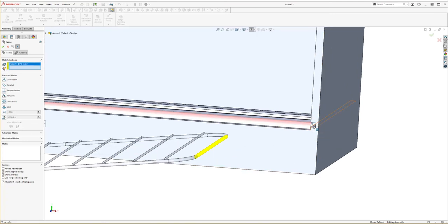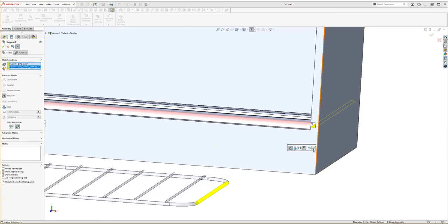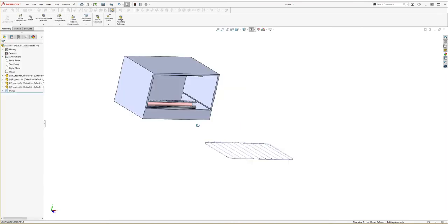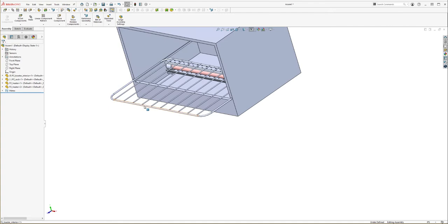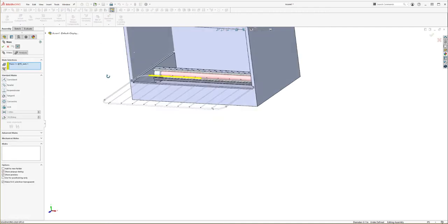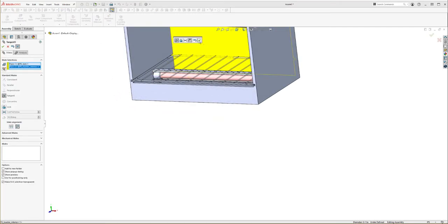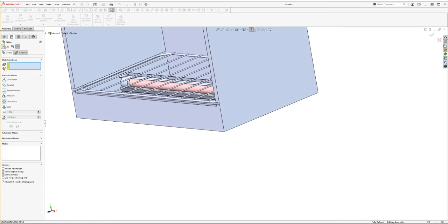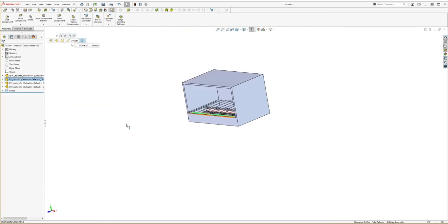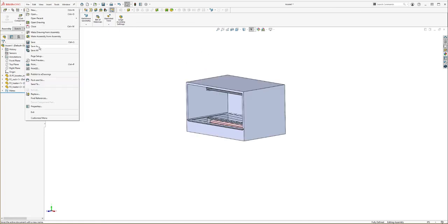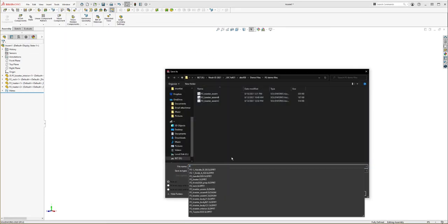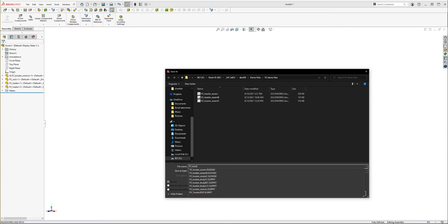So you may get an error if you try something like that. Try a different element to connect it to. And now we have a rack that slides in and out. Maybe you don't want that. Maybe that's annoying that it's sliding. You can always then mate this final back cylinder to the back face. And now at this point, this should be fully defined and it can't move. Yeah, and then when you're done, you can save this as your toaster interior.